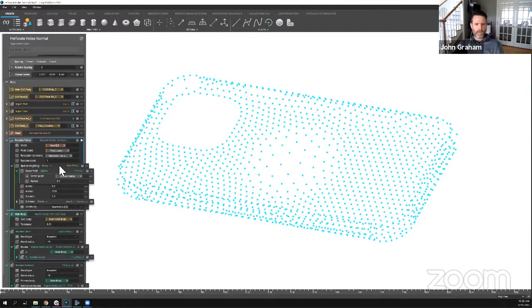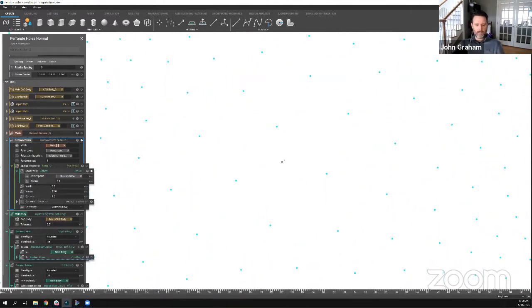Here it is. It's a ramp. This is probably my favorite thing in nTop, this whole ramp block, right? I created, you can see it on the screen, a really, really, really tiny sphere. Okay, it's sitting at the center. And I've told the system, whenever you are right on the edge of the sphere, the relative spacing should be 1, okay? Then I've said, let me change the color to like purple here. Whenever you get really far away from the sphere, and I used a function to do that, then I want the relative spacing to be 25. This was just the way I happened to set it up.